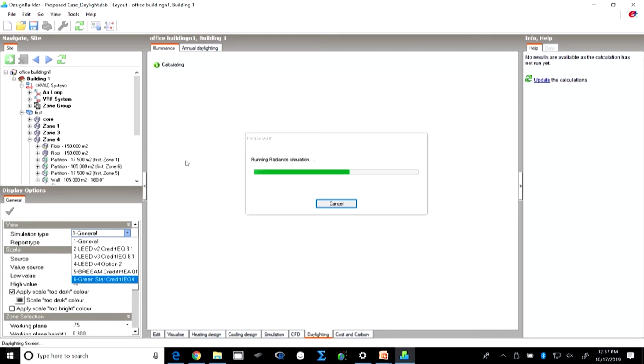If I know clearly the fundamentals that okay, north is the side where I want to provide fenestration, but I was not very clear whether I have to provide a clear glass or I can provide a tinted glass or I should provide a low-e glass, this is an interesting way to look at this. So, we will simultaneously be looking at the daylighting calculations and also the energy implications of that.